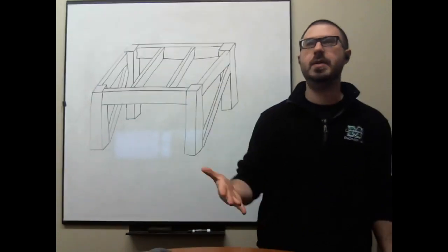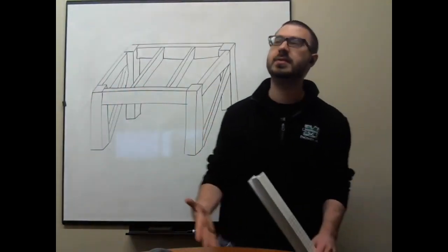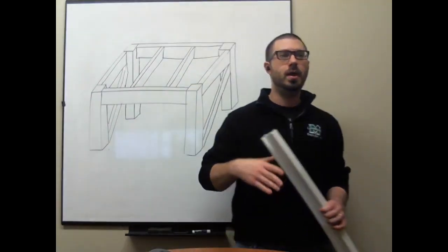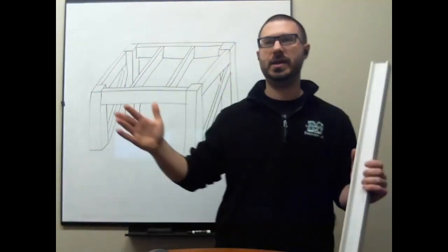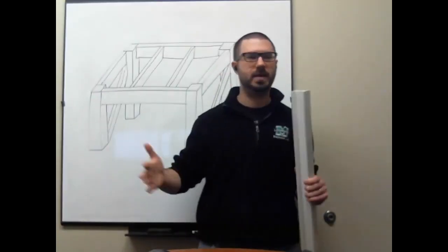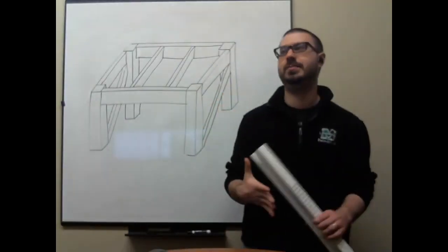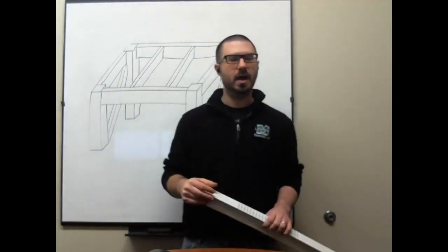Tension members are just that. They're members subjected to tension. And traditionally, whenever you start to learn steel design, you always start with tension members for 2 reasons. One, the mechanics are easy. If you look at the big picture of steel design and structural mechanics and structural engineering, tension members are a very easy place to start. You have sigma equals P over A. If you understand that, you understand tension members.